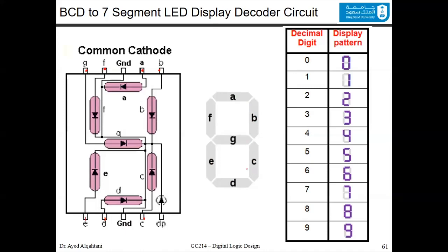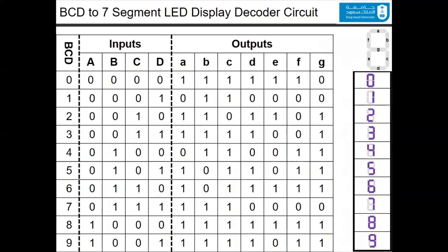So to do this circuit, using the techniques that we studied, we have to generate the truth table. So the inputs will be in binary. You have 4 variables, A, B, C, D, and you generate this simply by 0, 1, 0, 1, 0, 1, and so on for D, and C is 0, 0, 1, 1, and so on.